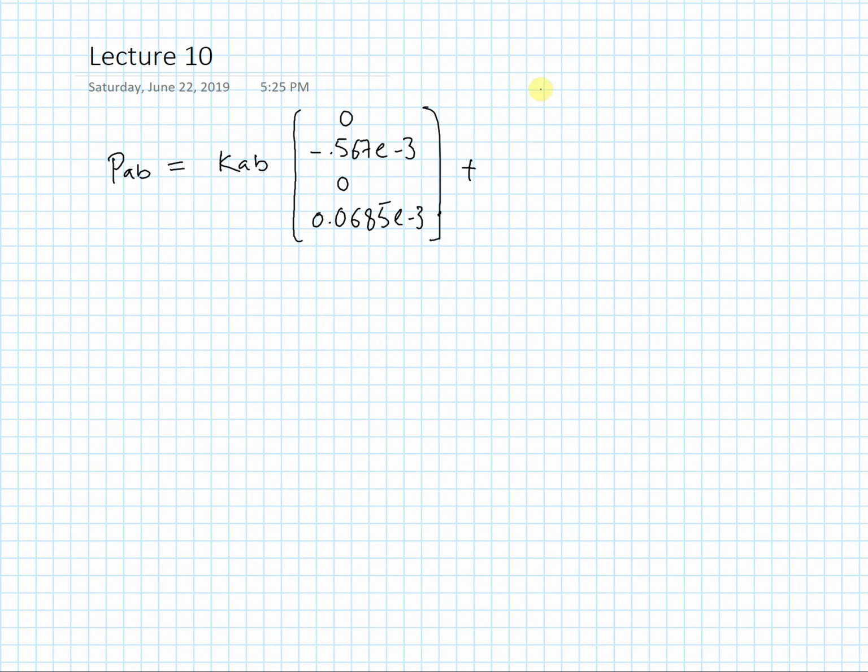I had this 8 going up. This is the rotational one. With the stiffness method, we said counterclockwise is positive, so 10.67 is going to be positive. We have a value of 8 and a value of 10.67, and it's a minus.